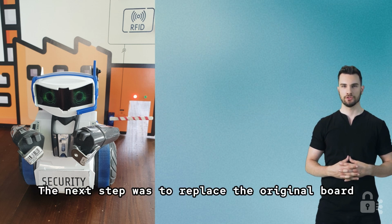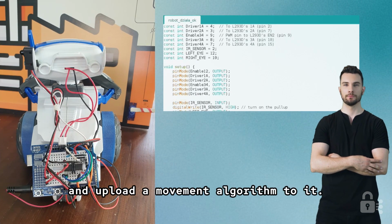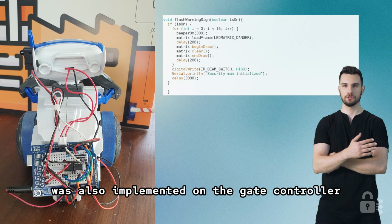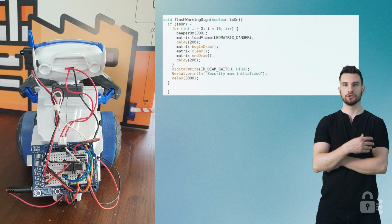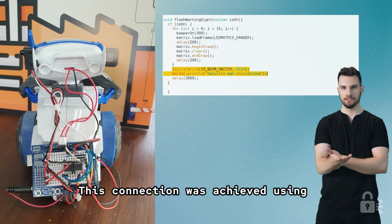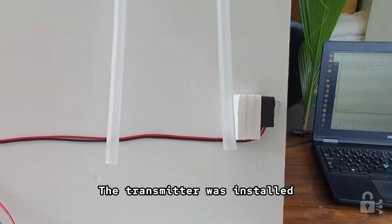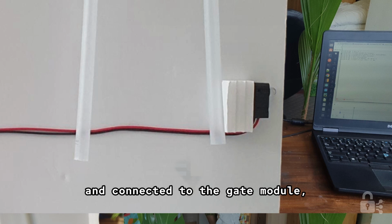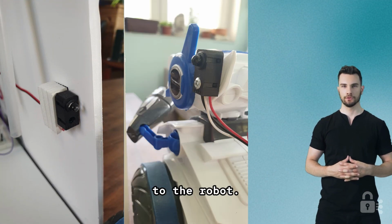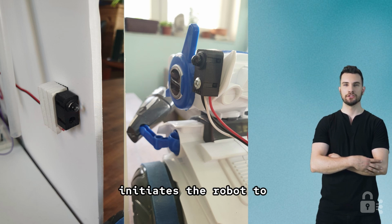The next step was to replace the original board with an Arduino Uno module and upload a movement algorithm to it. An appropriate piece of code was also implemented on the gate controller to establish the connection between the gate and the robot. This connection was achieved using an infrared beam interruption sensor. The transmitter was installed and connected to the gate module, and the receiver was attached to the robot. From now on, triggering the alarm initiates the robot to execute its code.